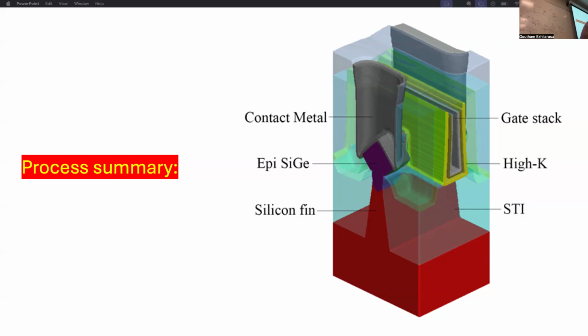So there are two things I haven't included here that I expect you guys to include. One, I haven't done silicidation. You have to do silicidation on the source and drain, right? That's one I haven't shown. The other one is the lightly doped drain, but that's just an implant and edges. So that's two things I haven't shown here. I didn't count how many steps. Just leave it at that.